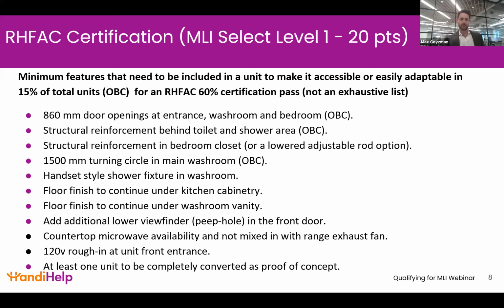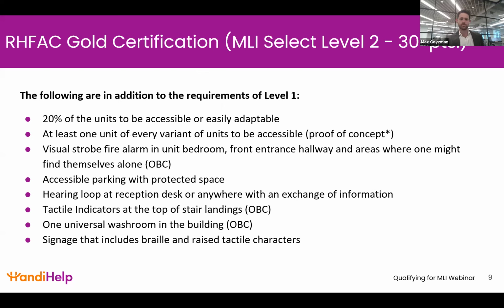And I also want to clarify, if there's a commercial building that gets gutted down to base building and is now going to be renovated to be residential, even though the existing structure of the building exists, because of the level of new build, it's considered a new build. So that will require 1200. It cannot go under the 1000 millimeters.